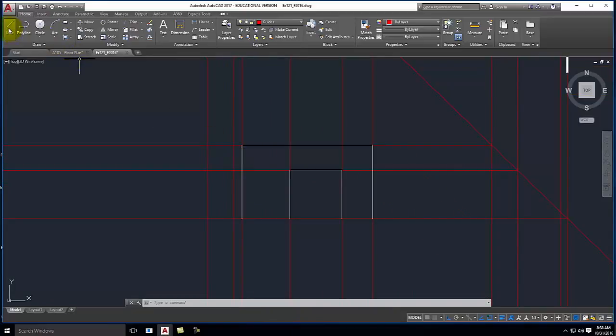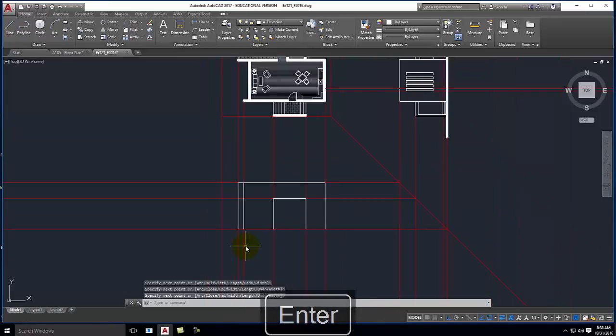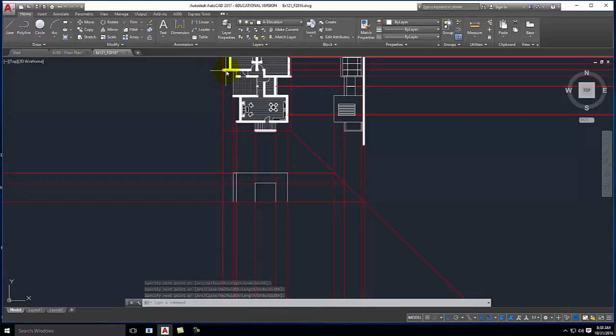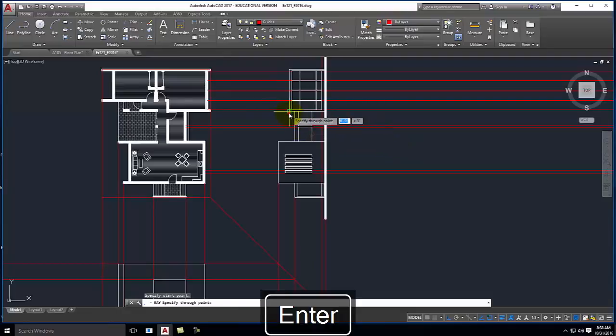So I'm going to go ahead and draw up on my elevation layer, up from right there to right there, and connect those two because they're part of the same little building. And then this building has a height of this. So let's use my guides, and we'll type array, and we'll go to that point.